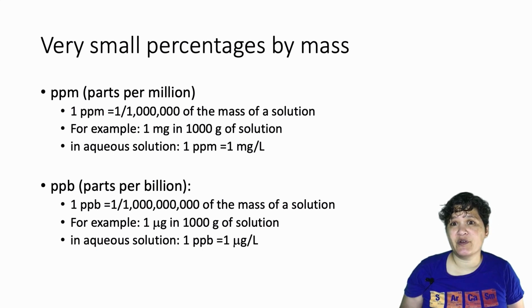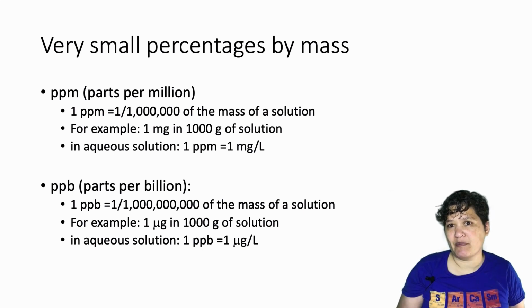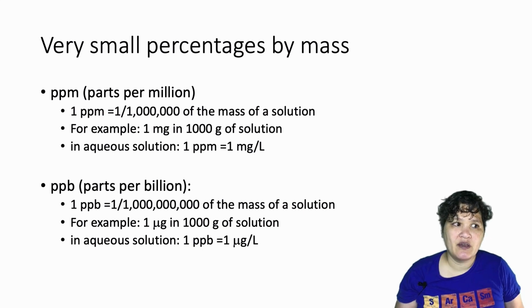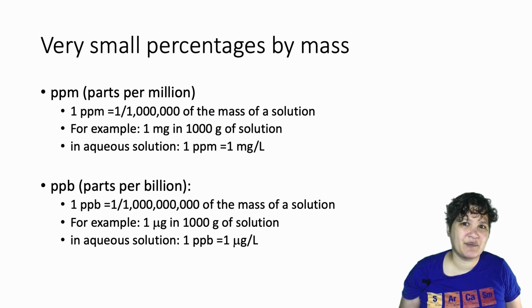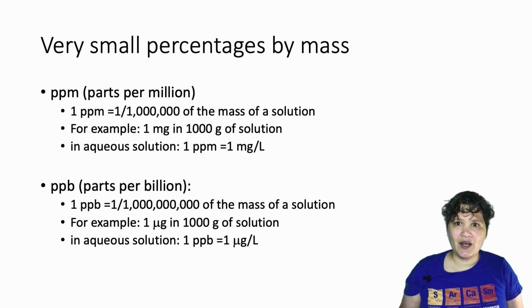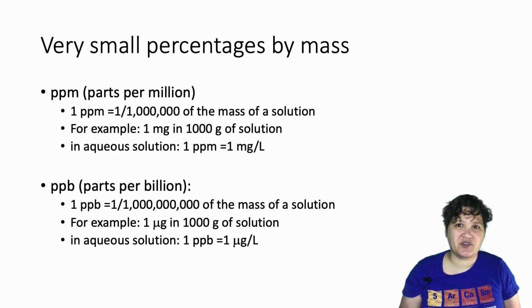There are some things where you're not allowed to have more than a certain amount in parts per million of dissolved something. And there are things where you don't want to have more than X number of parts per billion in your drinking water. So for example, lead, I think it's like 10 or 15 parts per billion is the upper limit. Obviously, you don't want a lot of lead. You want a really, really tiny amount of lead in your drinking water.